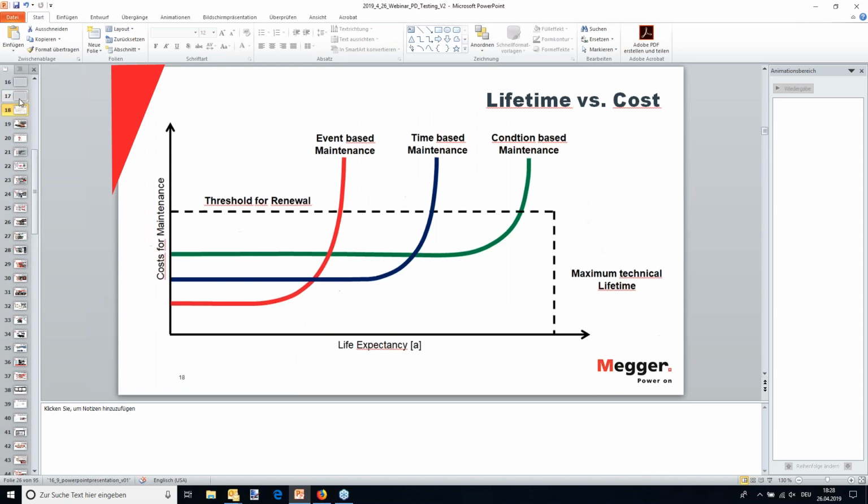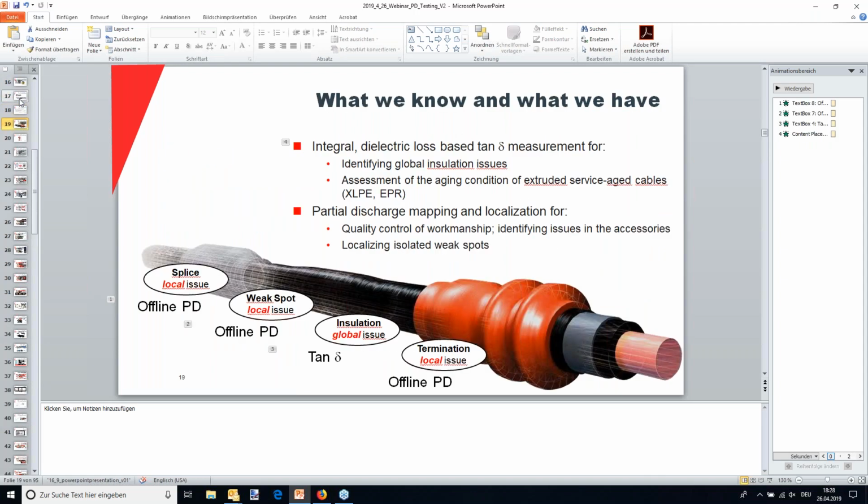When you think about the cable, there is PD kind of everywhere in the power industry. Transformers can have PD, terminations can have PD, some form of PD is corona, PD in gases, external PD on transmission lines. So PD is nothing unusual, nothing specific to the cable.